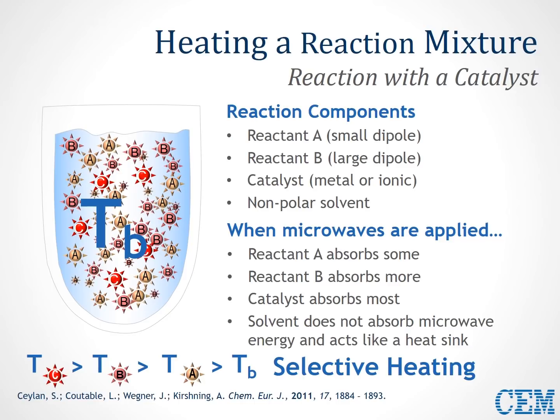Without stirring, hotspots can occur in areas where the catalyst may have settled in your vessel, which can possibly damage your vessel, and it's highly likely that your reaction will result in a low yield.